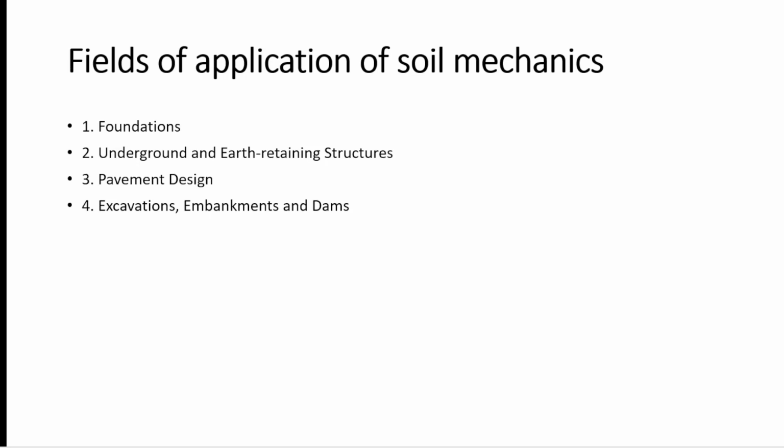The third one is pavement design. Pavement design may consist of the design of flexible or rigid pavements. Flexible pavements depend more on the subgrade soil for transmitting the traffic loads. Problems peculiar to the design of pavements are the effect of repetitive loading, swelling and shrinkage of subsoil, and frost action. Consideration of these and other factors in the efficient design of a pavement is a must, and one cannot do without the knowledge of soil mechanics.